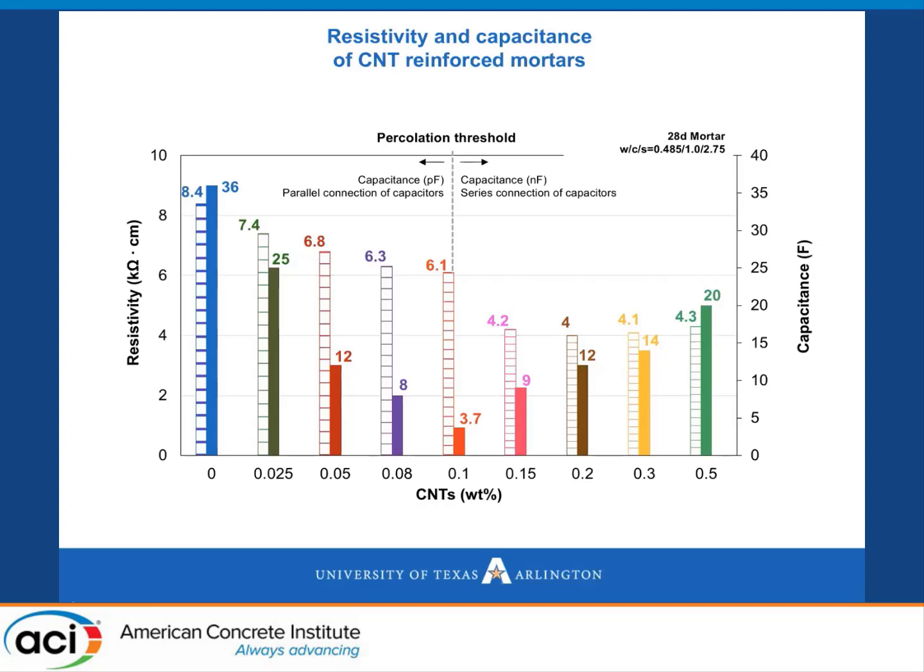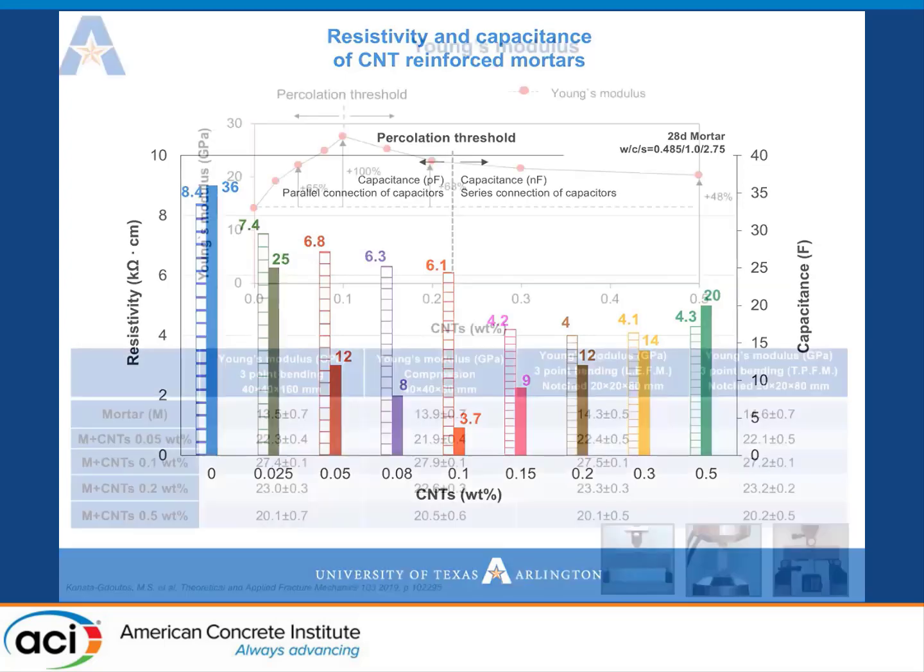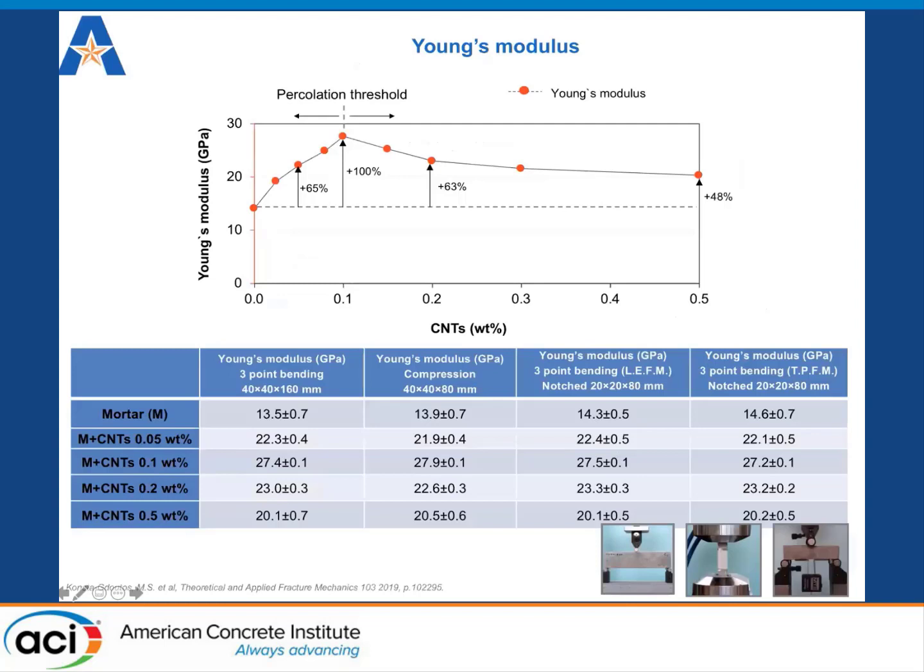Before I show you my final slide, with the correlation between capacitance and mechanical properties, I just want to point out that the values of the modulus that I'm going to show you here were measured from the 3-point bending tests on 4x4x16 prismatic beams, and the compression tests on the half prisms.